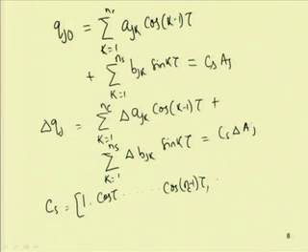For the sine part, for k equal to 1, the coefficient of b j 1 will be sin tau. So the first term is sin tau, then sin 2 tau, and the last term is sin n s tau. So, this is C s. One can write q j 0 in this form, that is C s into A j, and the delta q j term also as C s into delta A j.